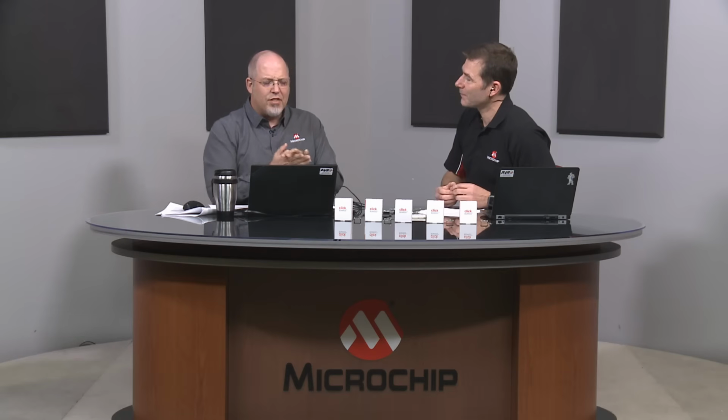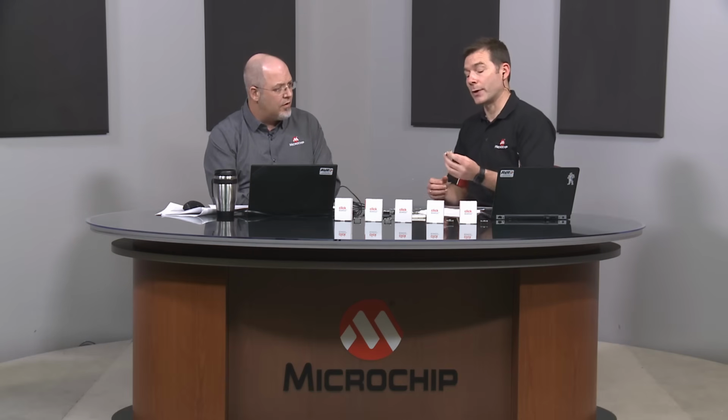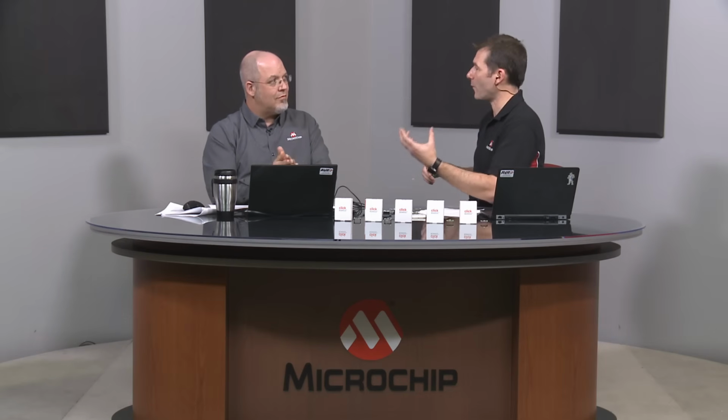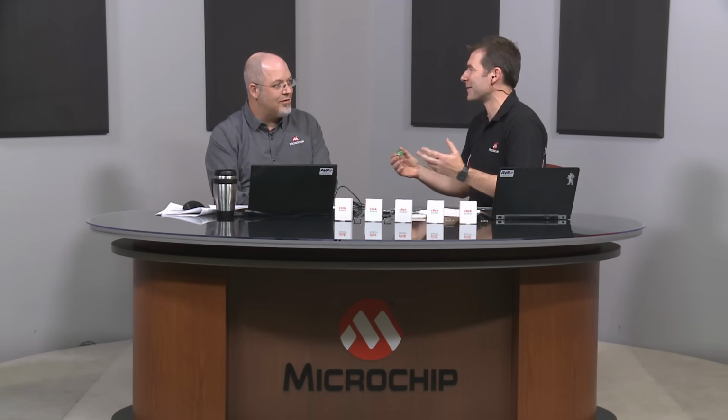And a lot of these clipboards make use of very common connections that you'd find on almost any microcontroller, right? Yeah, that's a good point. What we have here is a standardized interface, defined by MikroElektronika. They have put up some connectors here. They have serial communication, so that would be I2C, SPI, UART, and also a little bit of analog and reset. These are standardized serial interfaces that you use in most applications for inter-peripheral communication or communication on board. Of course, if you go off board, it would be other things: USB, Ethernet, and so on.